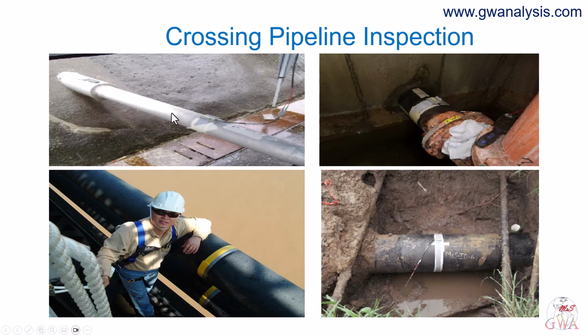This slide shows the MsS coupled to pipe surface using epoxy in one case and shear couplant in the other. We have 2 coupling methods, and they are for 2 different jobs. Shear couplant is used for one-time inspection. It goes on quickly. It lets you install the probe around the circumference easily, and it gives excellent coupling for the hours you need it. Epoxy bonding is used when the probe is going to stay. It holds the strip for years.